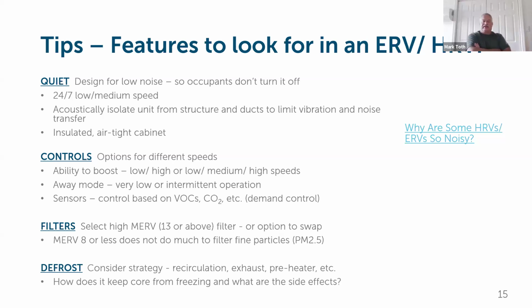So how quiet is it? That's very important because we want the people to run them. The last thing we want is a noisy system where the homeowner is going to shut it off. And there's also different designs there. You can have a 24/7 low speed with a boost. You can have intermittent operation. The units themselves, some of them are insulated better. Some of them have heavier cabinets. Some of them have quieter motors. Just the whole package. You've got to really look for the one that is going to be specific for your application, what's going to be best. But definitely having them be quiet is extremely important because if they're not, the homeowner is going to shut them off and not have proper ventilation.